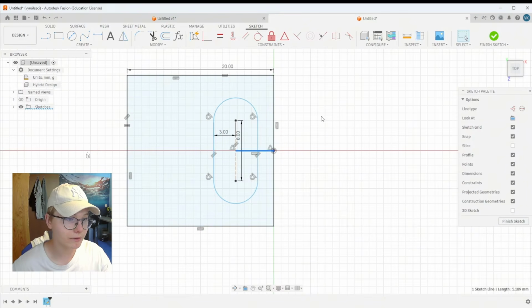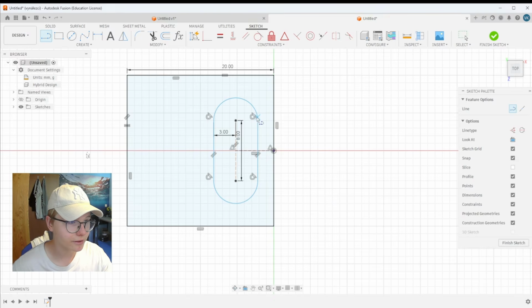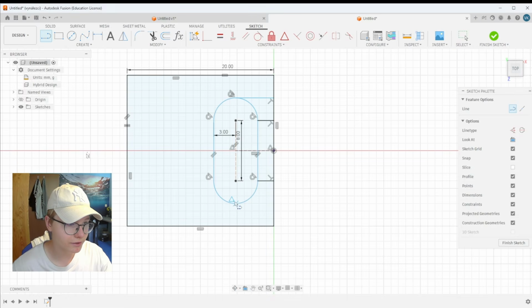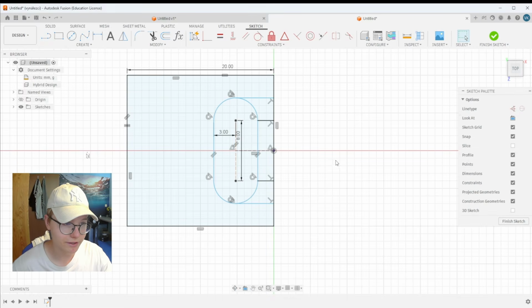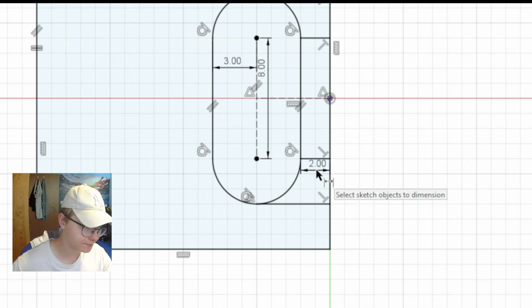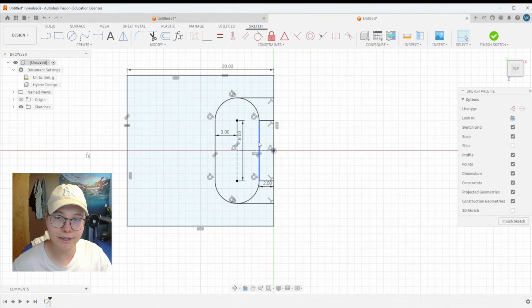So once you have that, we can actually start setting the distances of this slot so that it can have everything constrained. So I will make one of the lines over here and the second one over here, and then because we need even the hole that the slot will be inserted with, I need to sketch even these lines that will create the insert hole. Over here I want this distance to be 2 millimeters. Of course, as I said, you can completely customize this to yourself.